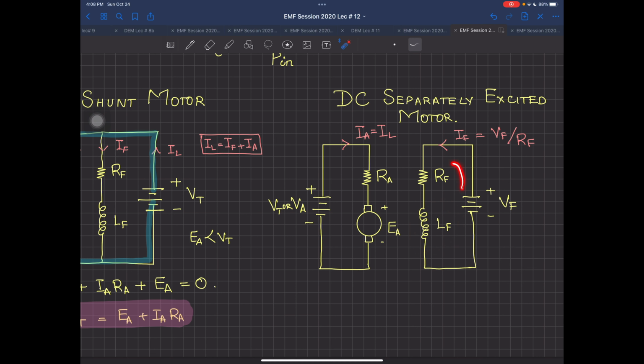And you all know whenever a DC current is flowing through an inductor, it behaves as a short circuit. So all this analysis which I am doing is steady state analysis, not at the point when, maybe, I have a small switch and I just turn on this switch. There will be some transients developed inside the inductor, just like you have been doing in your circuit analysis course. So it is very important that whatever equations we have here do not take any inductance into account.